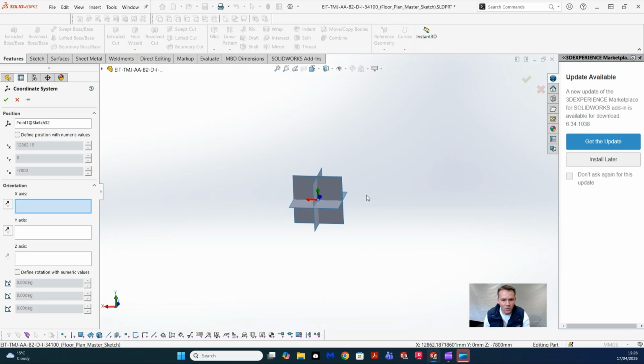In this case, because I've got these nice handy surfaces, similar to planes, we can click on that and you'll see it'll move those axis directions, and we can choose to reverse that or not, as the case may be. As you move on and make your selections in a similar fashion with different surfaces, you can manage these three axes to point in whatever direction you want, by using those references.